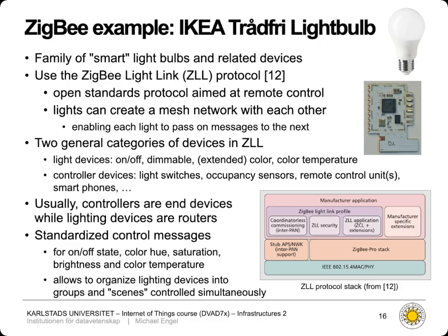Now, of course, you can do quite a bit more with a modern lamp. For example, you can have multicolor LED lamps here, so you can control the color. You can even control color cycling. With monochrome lamps, you can dim them using pulse width modulation, or you can control the color temperature by enabling a mix of warm and cold white LED lights.